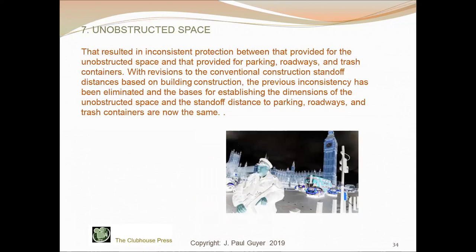Those earlier standards resulted in inconsistent protection between that provided for the unobstructed space and that provided for parking, roadways, and trash containers. With revisions to the conventional construction standoff distances based on building construction, the previous inconsistency has been eliminated in these standards, and the basis for establishing the dimensions of the unobstructed space and the standoff distance to parking, roadways, and trash containers are now the same.